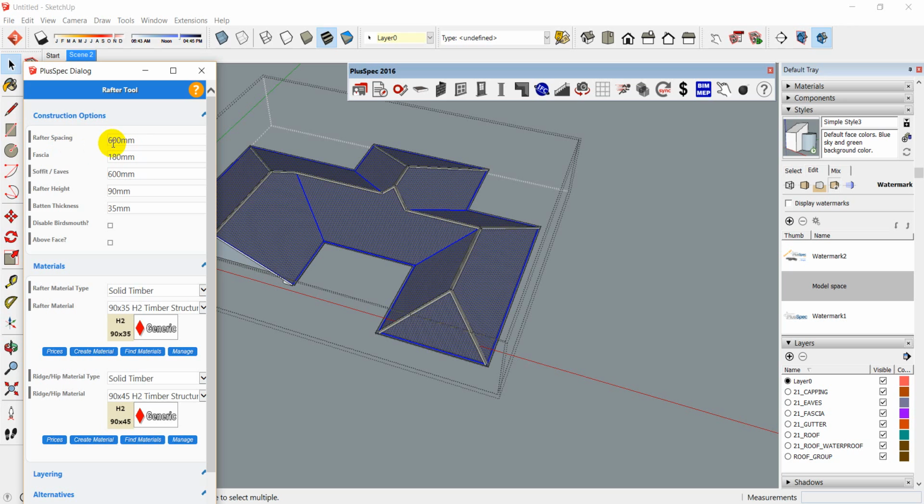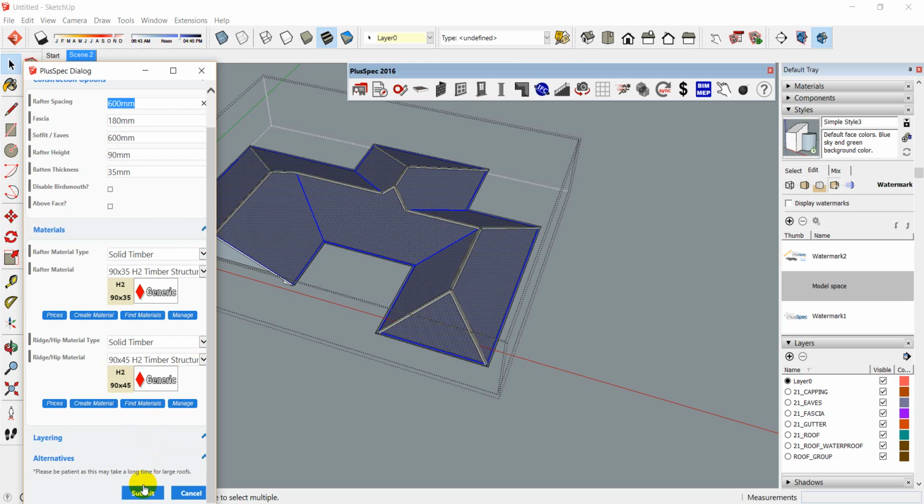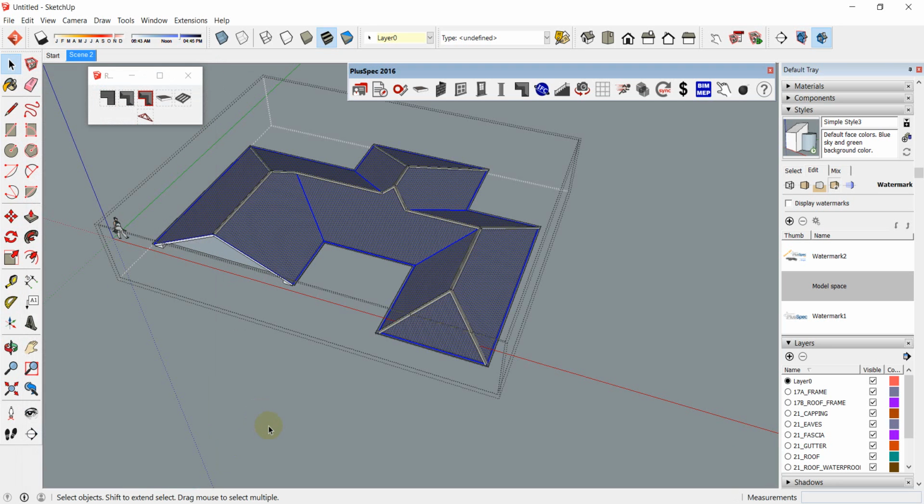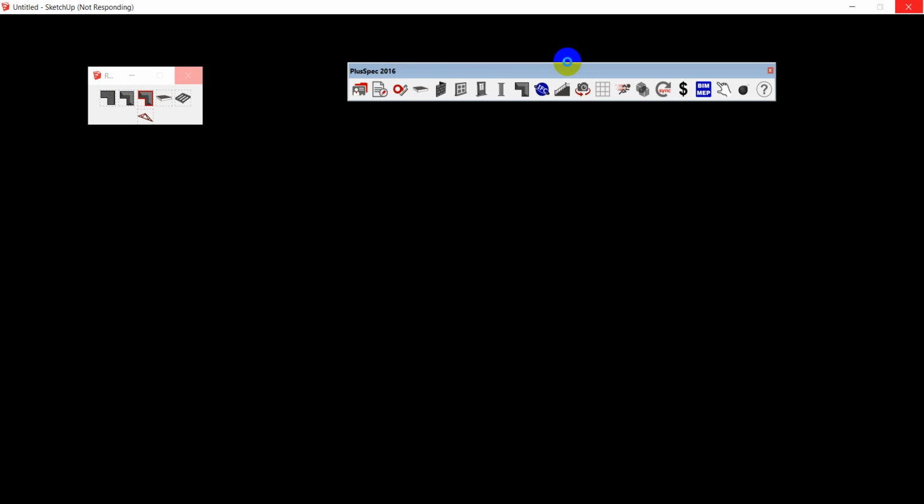So we've got the rafter spacings and fascia. I know that Canada's imperial and metric. I'll leave it in metric, but if you want 2 feet, simply write in 2 feet, for fascia height and so on, and the size of your rafters down here. You can choose a metric or imperial option there as well. Okay, and we simply go submit. Now it's going to take a second, so let's have a look at what happened behind the scenes. I'm going to create all my scenes again. See them happening up here. Now it's going to create a scene called structure.